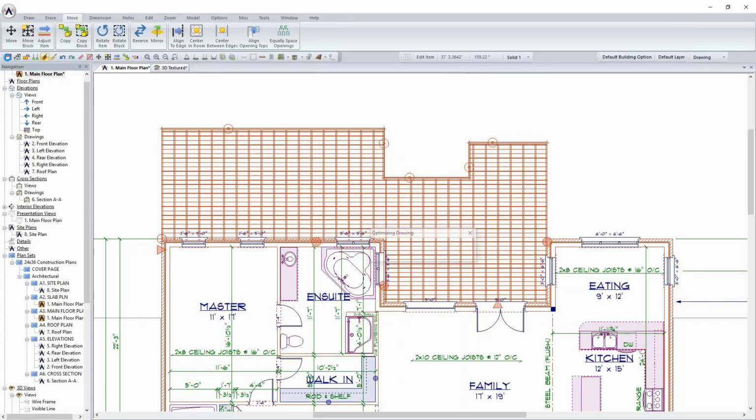I'm going to run a cleanup and a save at this point, and when I do that, I can now go in and begin the dimensioning of the deck. So all we've done right now is just simply sketch it in, explain what the reference circles do, and how you can modify the direction of the joist as well as the deck surface based on where the reference edge is going to be.